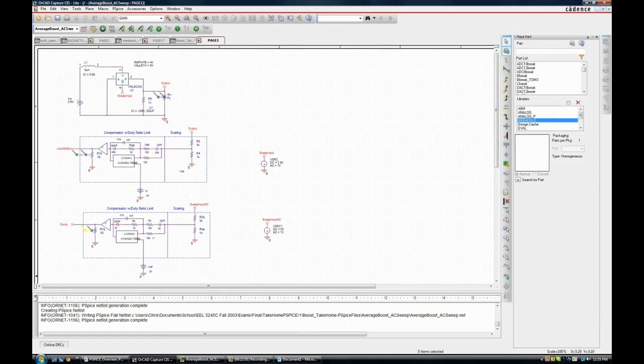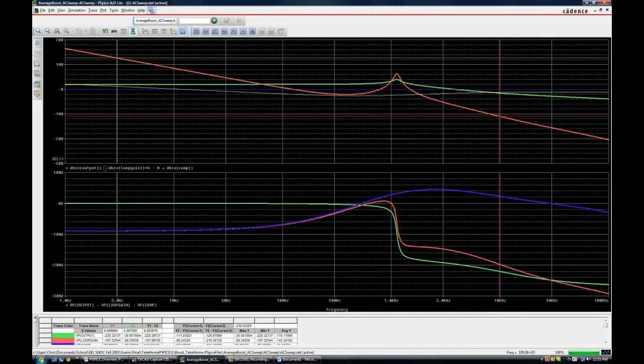We look at the transfer function from control to output, from the sweep output to output, and then from output to loop gain. You can see that the red here is the compensated loop gain. When we talk DC to DC converter control, I'll explain how this is a more desirable transfer function, and the gain and phase margins are both stable on this converter.